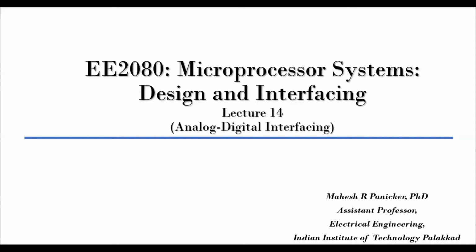And then we went into the discussion on serial communications. We had 3 separate lectures, one on the asynchronous protocol, which is UART. Then we discussed the 2 synchronous protocols, SPI and I2C, and discussed among themselves what are the merits, demerits, and how you go about it. I just want to ensure that you understood they are not limited to these 3 serial communications. The modern day communications like Ethernet or USB or CAN bus that they use in automotive control, everything is based on these simple serial communication protocols. So it's important that you understand them so that you can easily migrate to the other protocols with ease.